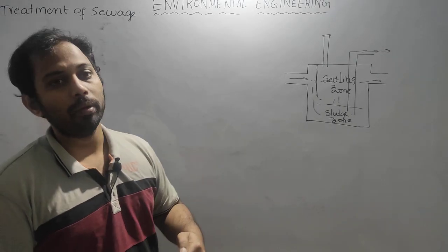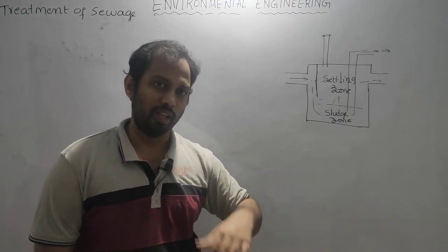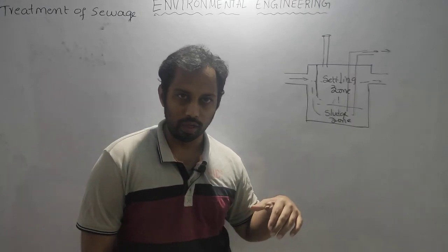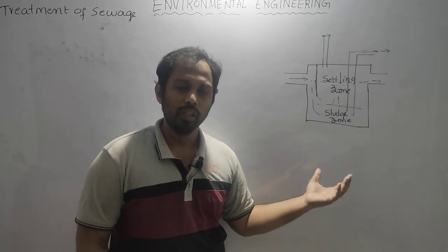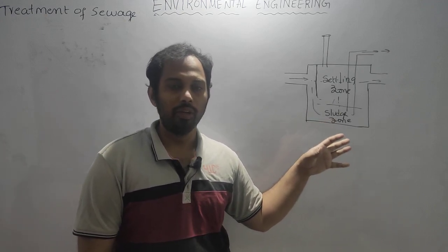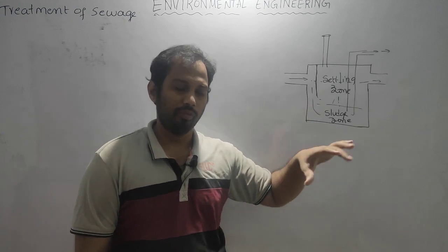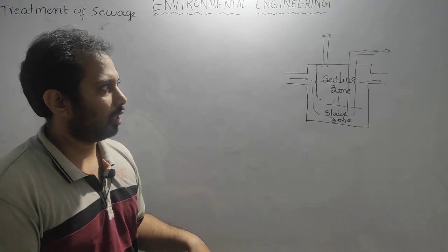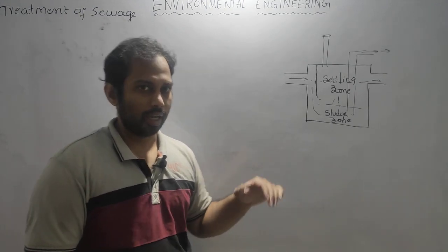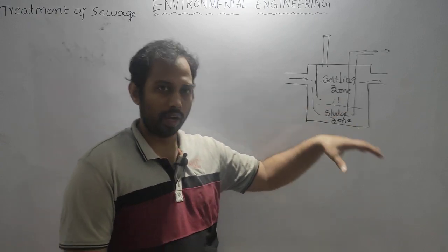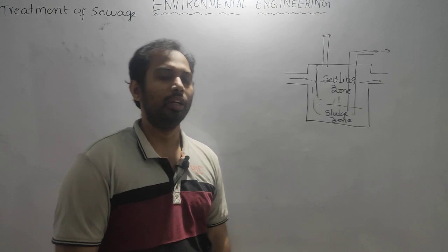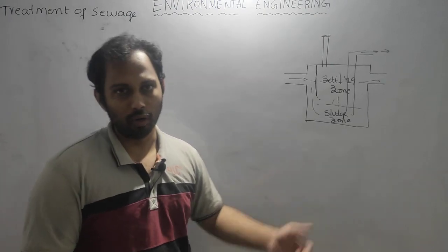In that condition, the septic tank will also collect the sullage, so domestic wastewater also we need to collect. If we are using it in a household, the sullage will enter the drain and only the human excreta will enter the septic tank. But if it is constructed for a village, for common people, then sullage will come into it. In that case the effluent may contain more BOD, which cannot be easily discharged into local rivers and drains.